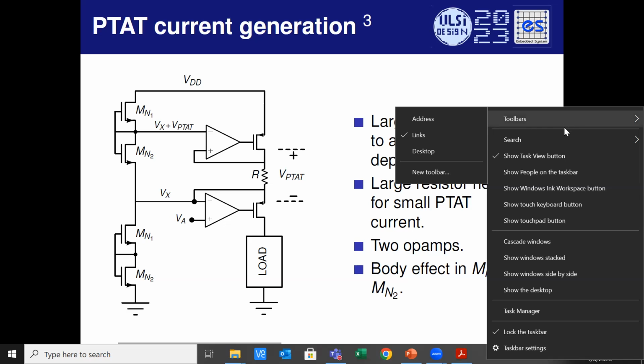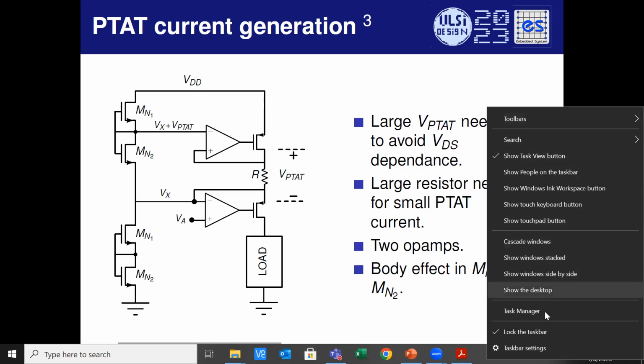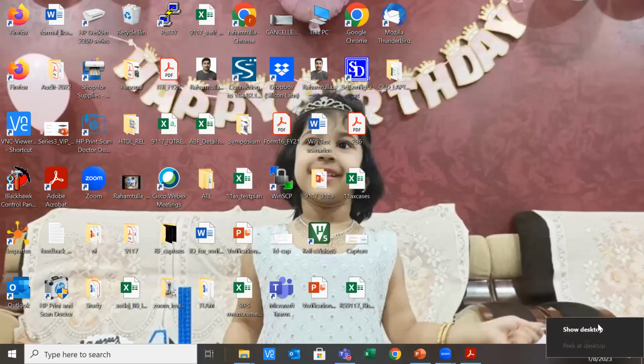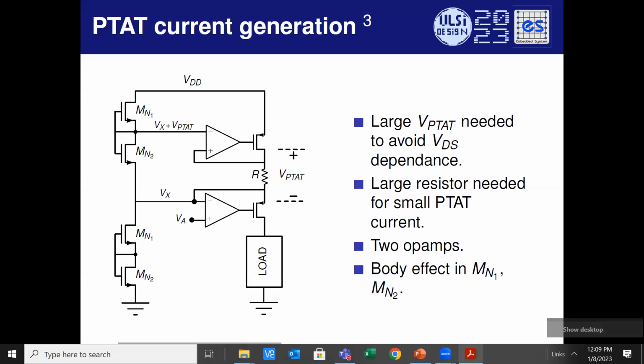Hello, can I ask a question here? Yes. In the previous slide, in the initial proposal, you said the PMOS and NMOS should have different flavors. Why is it? Because otherwise you won't get CTAT and PTAT, the two combinations. Otherwise you'll have only this PTAT. Like over here. So if you want PTAT, you can have the same flavor. Okay. Thank you very much.